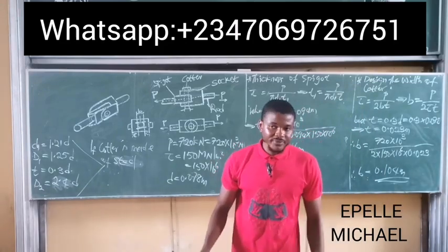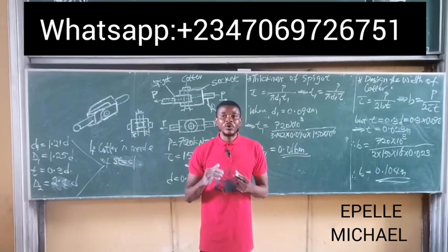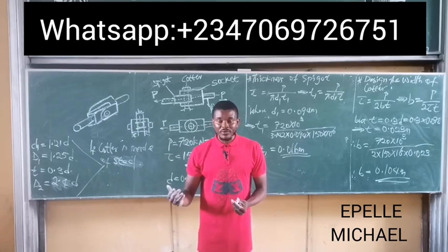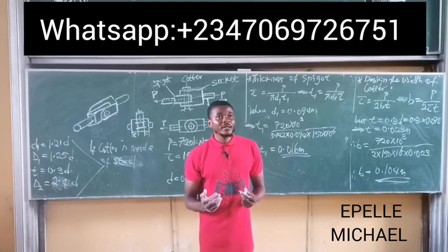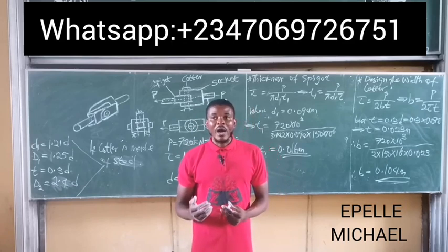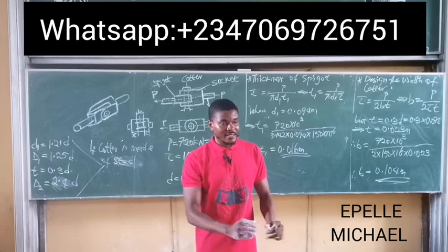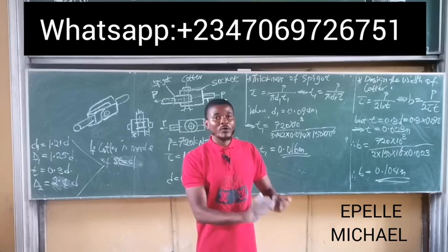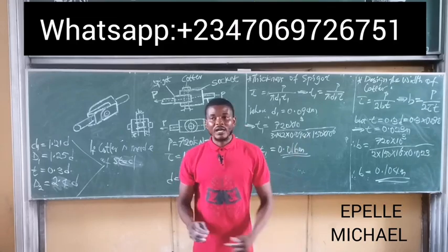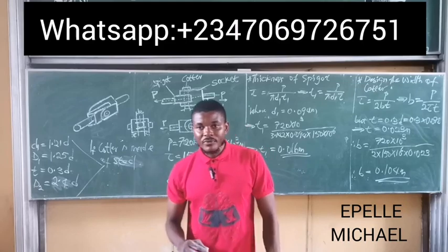Second question. So that's how you design a cutter joint when it undergoes shearing. A cutter joint majorly undergoes 3 kinds of deformation. It can fail by crushing, it can fail by tension, it can also fail by shearing. Among these 3, the question specifically said calculate the failure of the joint by shearing. So we're only going to consider the aspect of the cutter joint which undergoes shear failure. And those 4 are what we need to design to prevent failure by shearing. All right. Question 2.